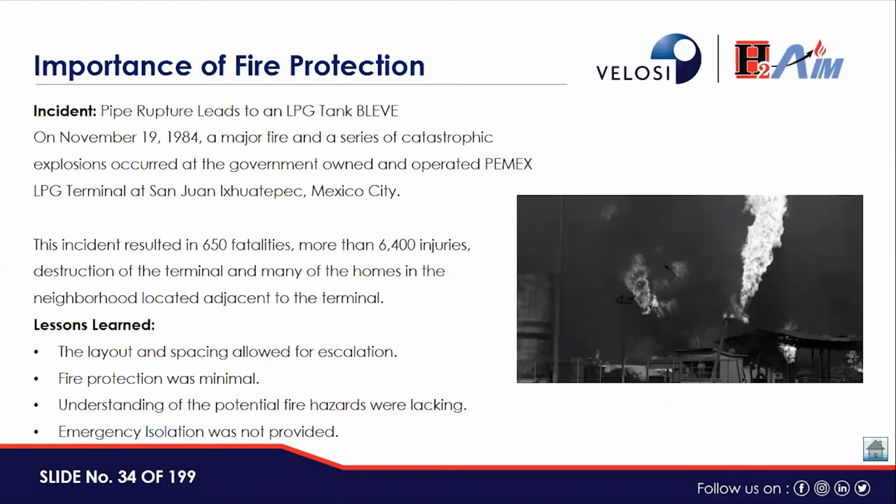What were the lessons learned from this incident? The lesson learned was that emergency isolation was not provided. Fire protection was minimal. The layout and spacing allowed the escalation of the fire, and understanding of the potential fire risks was lacking in the industry.